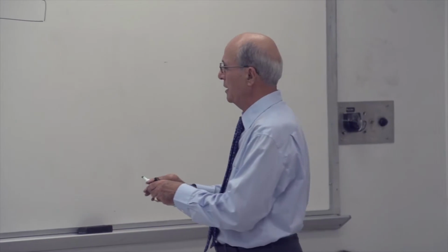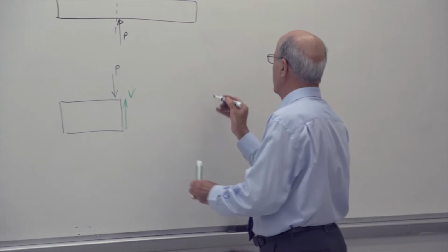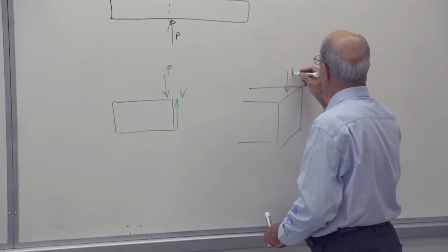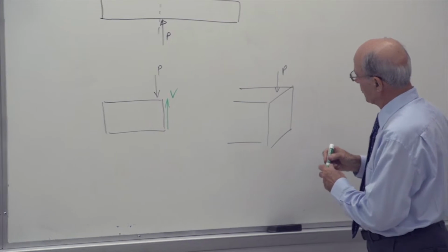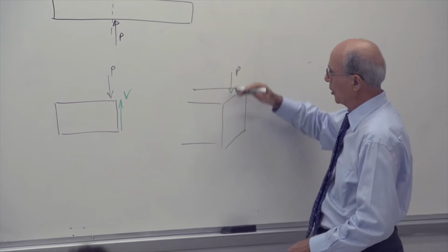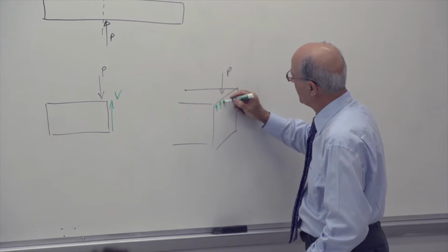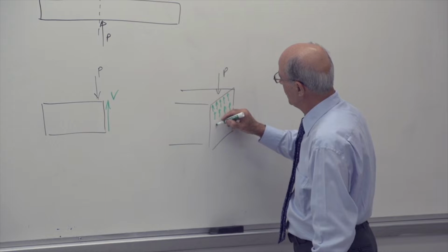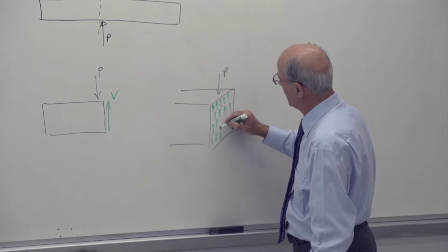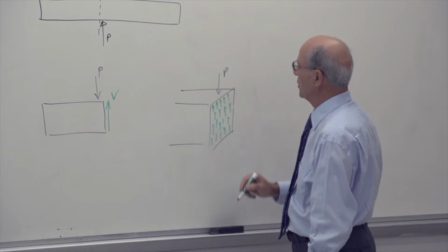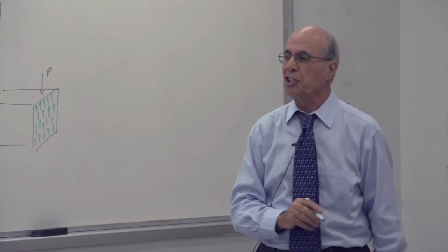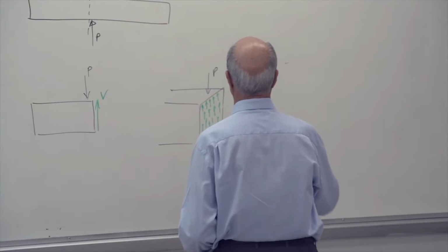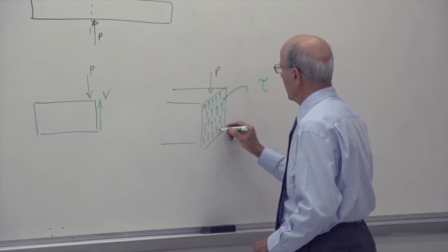So if I show that in the 3D scenario, let's say this was a rectangular cross section. So you have a P here applied, and then you have here stresses. I'm assuming the stresses, again, like last time, uniformly distributed. So you have here stresses not perpendicular to the cross section, but in the cross section, uniformly all over the place. Units are all the same per unit of area. So here is this. We call it shear stress. This time we show that with tau. I'm going to go back, show it there. So therefore, this is the tau. Let's put it here, and this is the area.